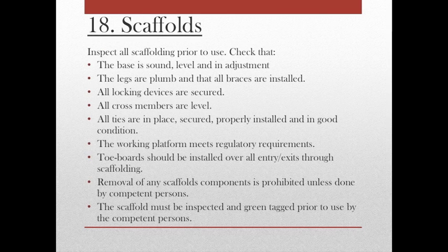Scaffold. All scaffolds will be erected and maintained in accordance with the manufacturer's specifications, Scaffold Industry Association, and OSHA regulations. Verify that the scaffold is safe and meets all regulatory requirements. Inspect all scaffolding prior to use. Check that the base is sound, level, and in adjustment. Sills, screw jacks, base is secured with a minimum of 2 nails as required. The legs are plumb and the braces are installed.